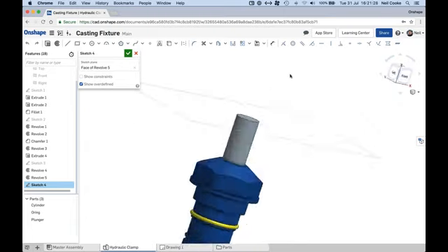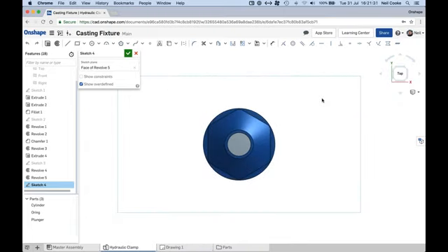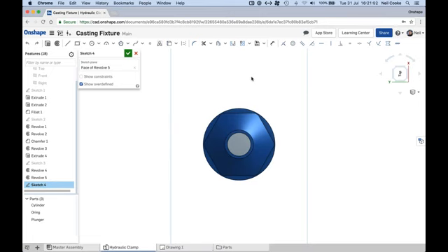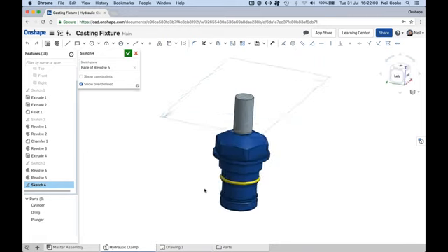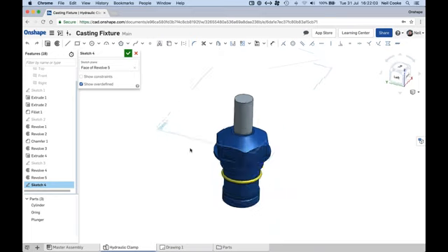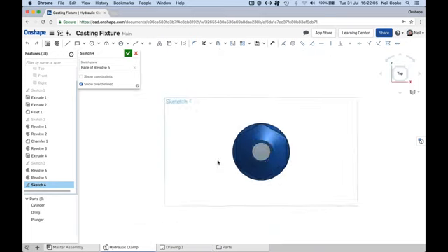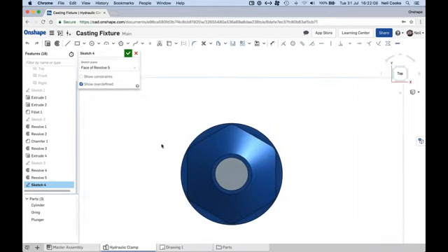But if I was rotating it and then pressed N, you'll see it's just going to go to the very nearest orientation. That doesn't really matter. There are a few cases where it does matter, but in general, it's not really a concern. The only time it bites you is if you've got it at perhaps 90 degrees and you're putting in a horizontal constraint when actually it should be vertical. But one way to tell which way up your sketch is, is the text on the plane which appears. That's not really a real plane. It's just a graphic to let you know which face you're sketching on and also the orientation of your sketch.